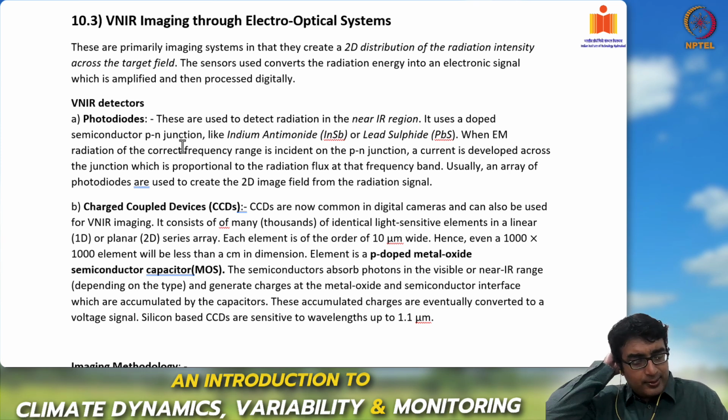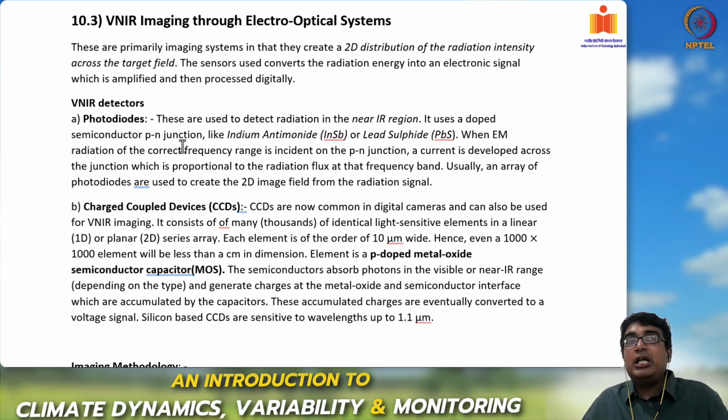Basically, semiconductors are certain materials that partially conduct electricity due to the presence of donor or acceptor bands caused by doping molecules. If you have a p-doped semiconductor, you will have a lot of positive charges or holes, and if you have n-doped semiconductors, you have a lot of free electrons. A p-doped and an n-doped semiconductor coming together creates a PN junction, which is the basic system working in every diode.